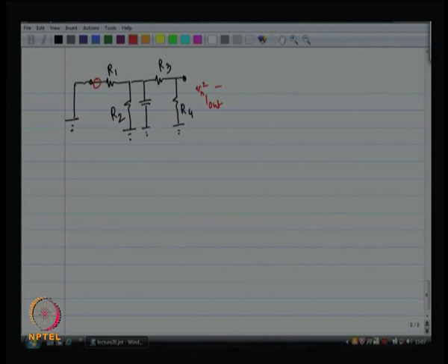Then do it for resistor number 2, then do it for resistor number 3, and finally do it for resistance number 4. And then you have to integrate all of these, presumably you have already got df inside your expressions, you have to integrate all of these over all frequencies. Okay. That will give you the total mean squared noise voltage over all frequencies.